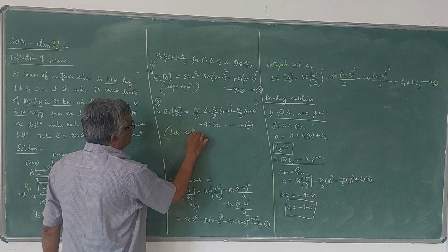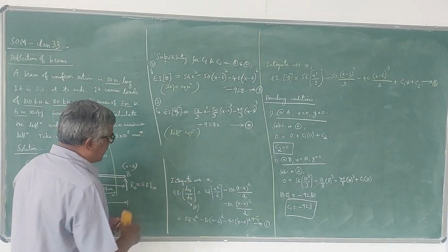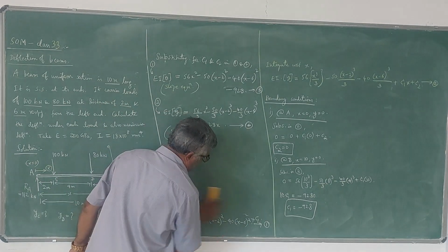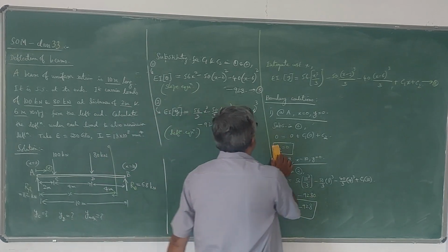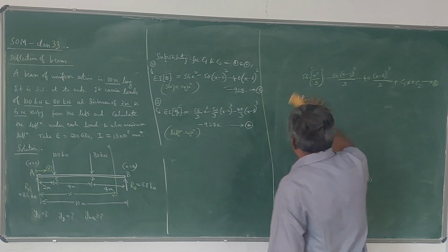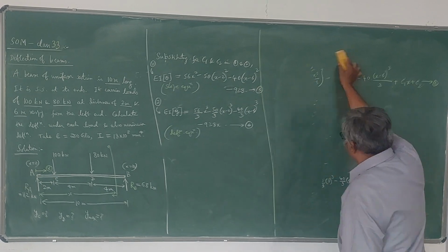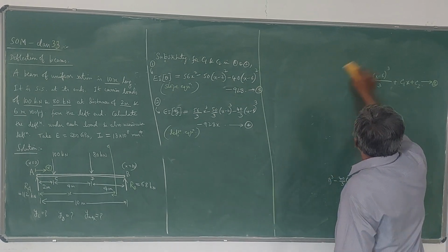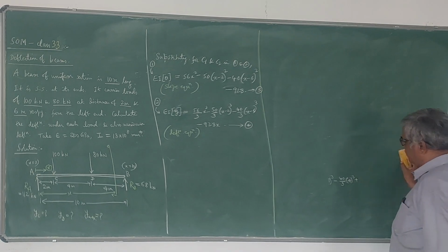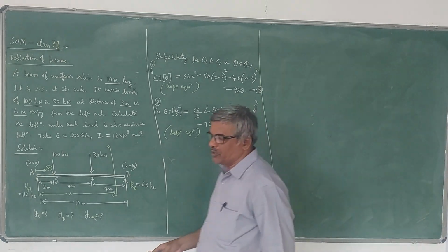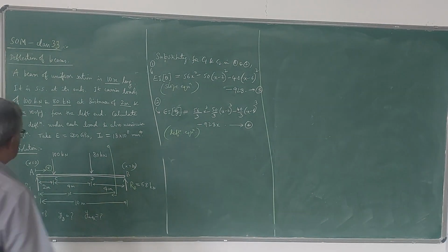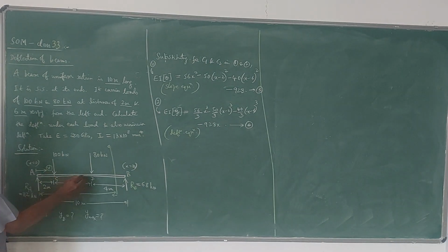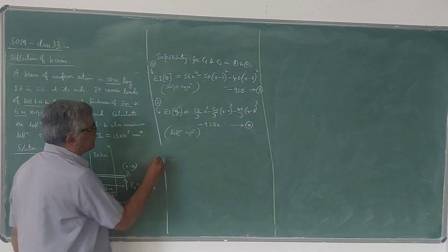Now just by putting the values of x wherever you may require and substituting and simplifying, we can get the slope and deflection at the required points. But one thing you should keep in mind is, if any term becomes negative after substitution for x, that negative term should be omitted. It should be neglected. That means it should be taken as 0. Yes, now he has asked the deflections under the nodes. That means yc and yd. Let us find out the first step.